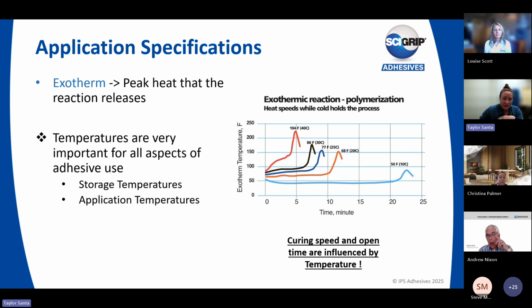On the other side of this, adhesives that are exposed to very high temperatures for an extended period of time will lessen the shelf life of the product. It's basically just speeding up the time you have to work with the material. Some types of adhesives need to be in freezers or heat boxes for best results, but the SCIGRIP MMA line just needs to be stored between 55 and 85 degrees Fahrenheit before use, so you kind of eliminate the need for adhesive freezers or specialty storage containers for adhesives.